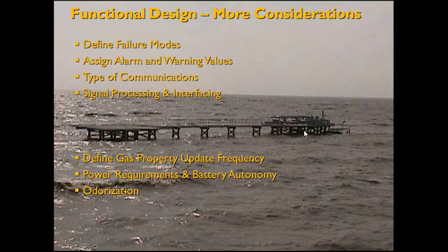And there's more. More things that we should consider. We need to consider failure modes, alarming. What are you going to alarm? What warnings will you set? What types of communications are you going to use? Here we see a platform. This was located on a large lake in South Louisiana. And one of the concerns I had about this site was how high this meter setting was from the water. It looks like during stormy conditions, this thing could actually go underwater.